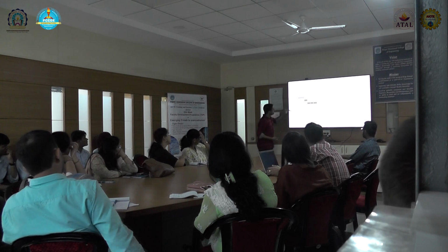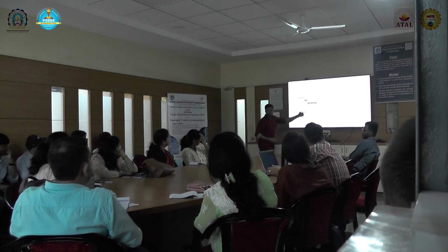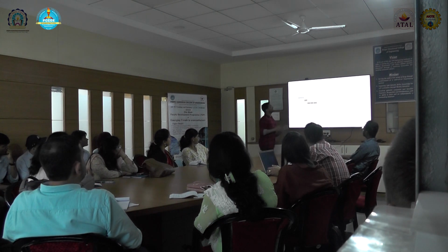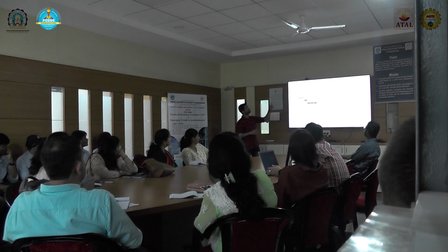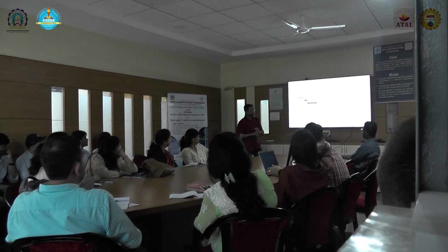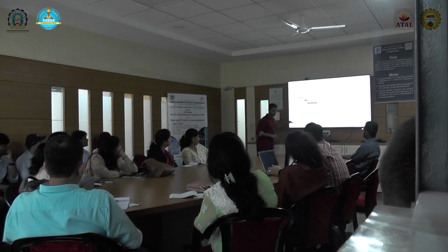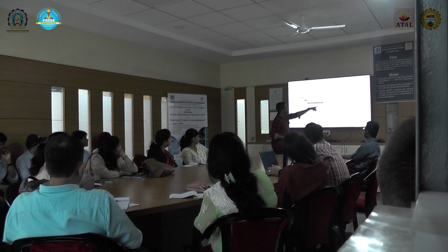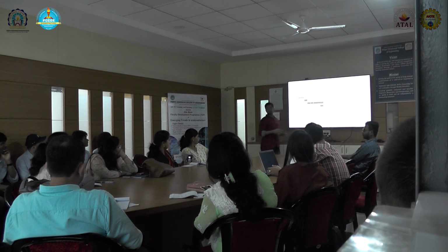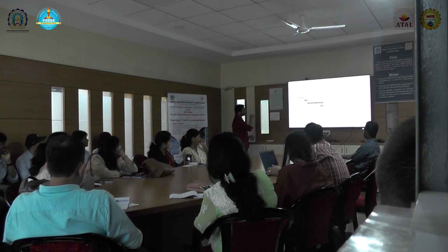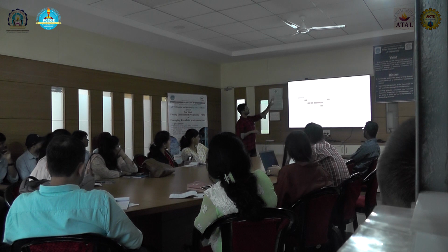In the next cycle, the green interface got done. But still, the main done is not high because we said that main done will get high only when both the done of green and yellow are asserted. So it's still waiting for the done of yellow. And once we get done of yellow, we will assert the main done. And as I said, after getting the done, the busy signal will go low. So this is the interface protocol for our design.